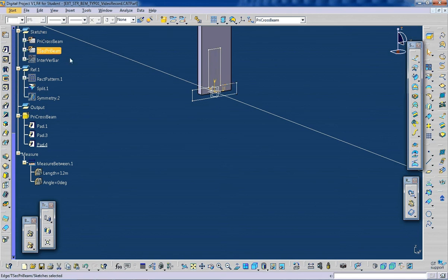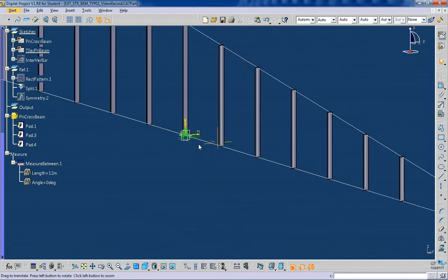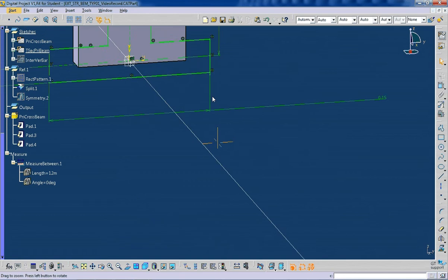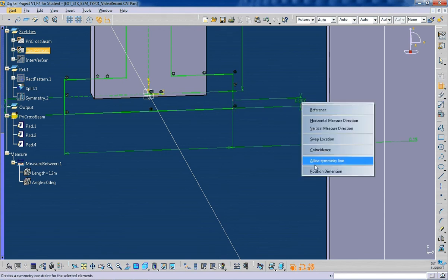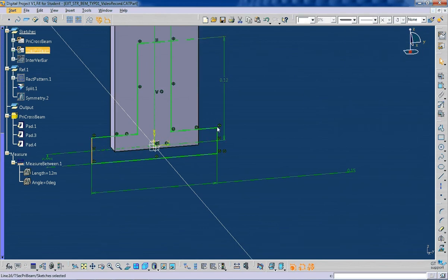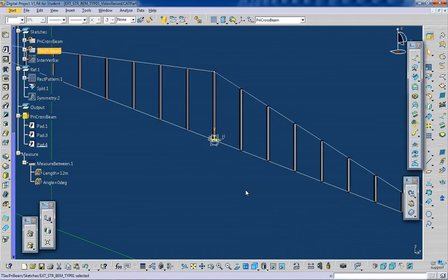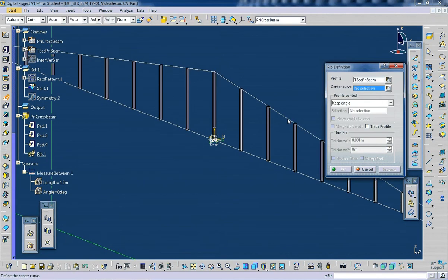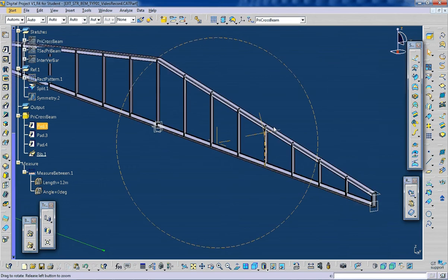This sketch 0.12. Alright, see here, it's supposed to be coincident to this point. That's what caused the problem. Just make sure this geometry is intact, fully enclosed. Okay, now let's redo that rib. Take profile already, curve will be this one, preview, good.